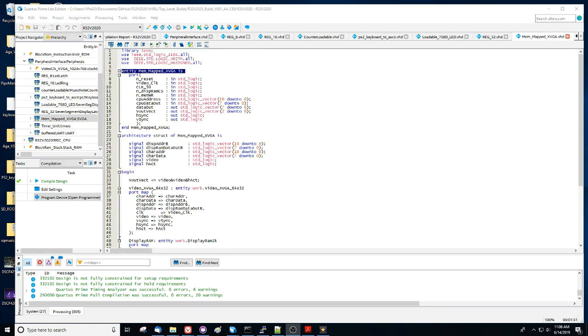One of the more powerful features of this is a VGA adapter. In this case, it's set up for 1024 by 768 video, and that corresponds in mapping to 64 characters per line by 32 rows of characters. And that interface is memory mapped, so to write to a character on the screen, you write a byte to that particular address. This allows for very, very quick operation. Screen clears take something like 4 milliseconds, which is 4 times faster than the screen itself is actually being scanned by the 60 Hertz video. So it's really, really fast.